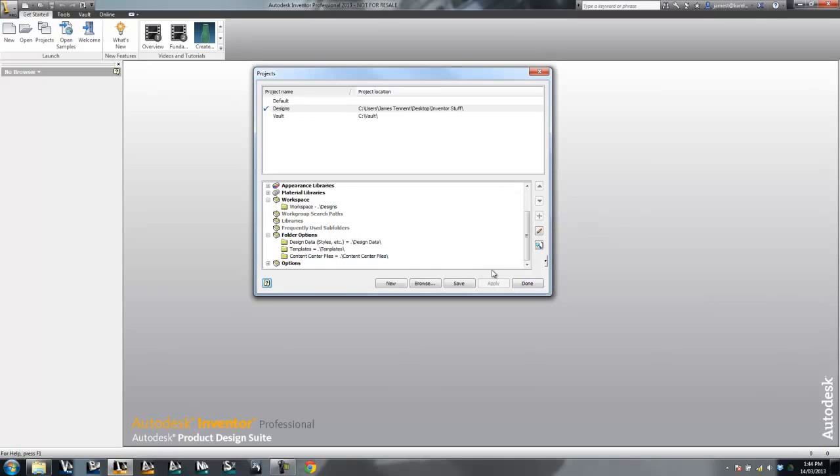That's actually a pretty cool feature. There was no design data in that folder, so it created some. That actually is pretty cool. Anyway, it doesn't do that with the templates. You get the idea. So look, the reason why I've done this tutorial is just to make sure that you understand that this guy here is so critical, and so is this guy. The rest of it is not as critical, because no matter what you do with the templates and these ones, you're still going to be able to open and resolve your files if you've got these two guys mapped.